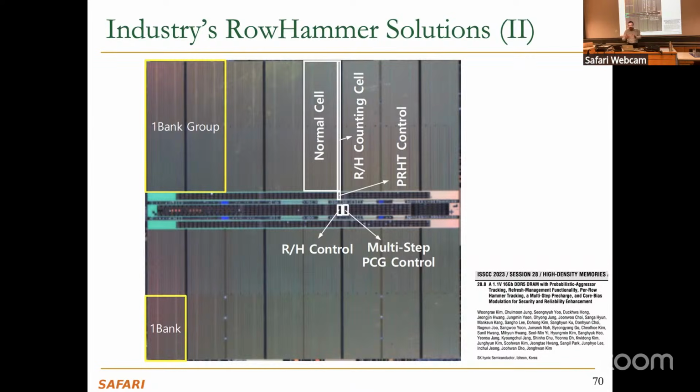I mean, solutions were in the right direction, but this is actually a more sophisticated controller in the DRAM chip. Right? DRAM manufacturers were very cost sensitive, so they didn't want to implement anything inside the DRAM chip, but they put this inside the DRAM chip. I would actually argue that it's not the best solution. It's expensive, in my opinion. You could do better with bloom filters, etc., all of those other solutions, but the fact is that there's an intelligent DRAM controller inside the DRAM chip.